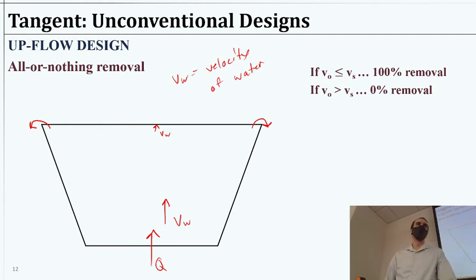That's not going to work too well for light particles that are going to be pushed by the water pretty quickly and essentially not settling very fast. So your V critical is going to be essentially equal to that velocity of the water going over it.